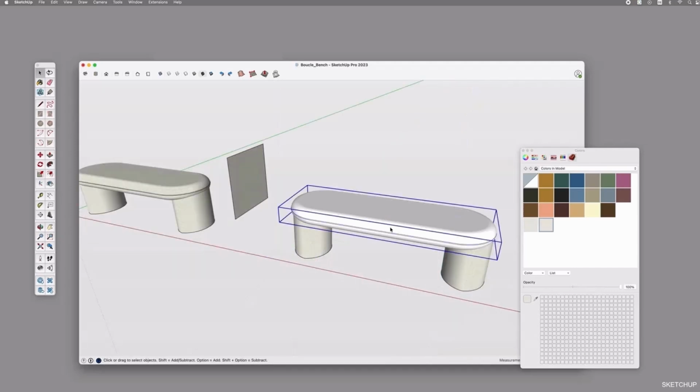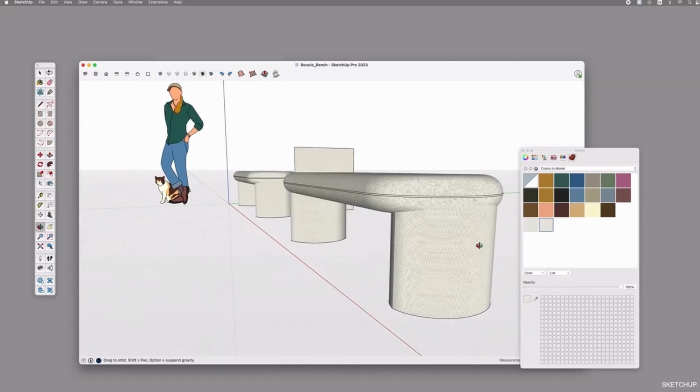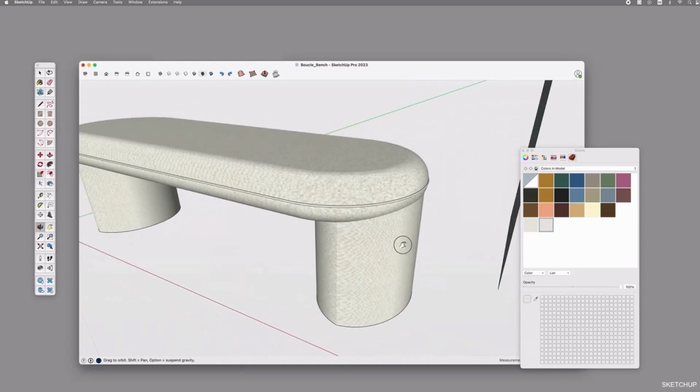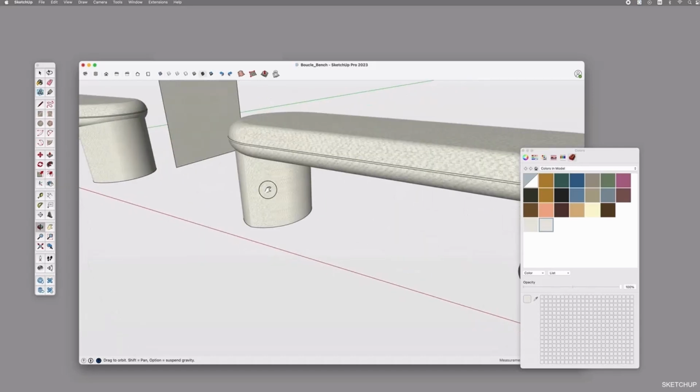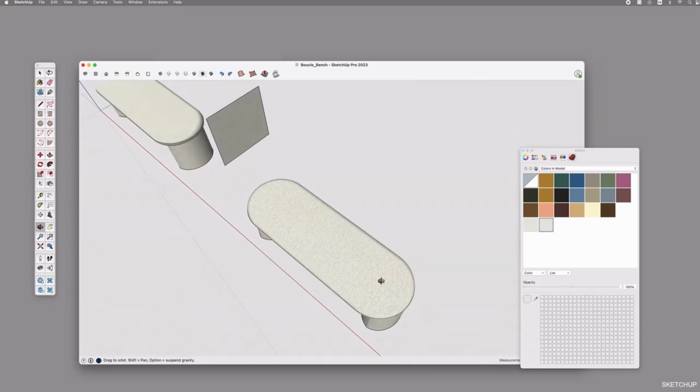Do you see the quality difference? This really can improve your 3D design outcome. So whenever you download something from the warehouse, just place the material on a flat surface, move it to the correct side so it aligns with the surface you want to adjust, and start projecting it onto the surface.